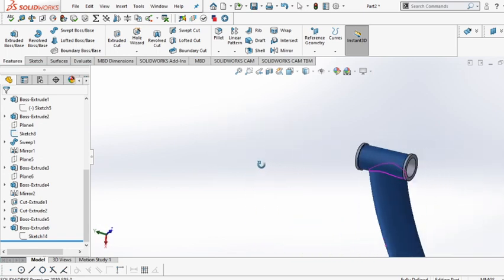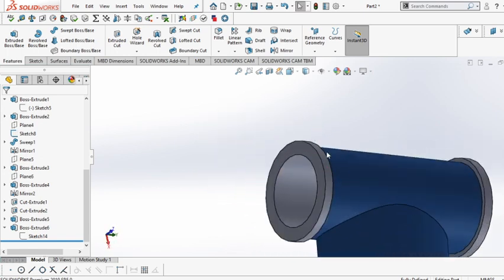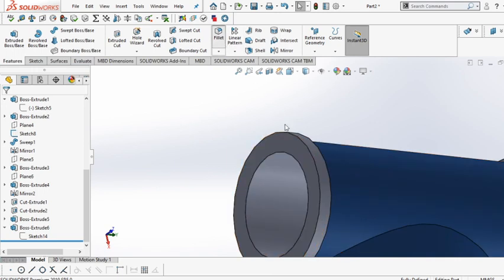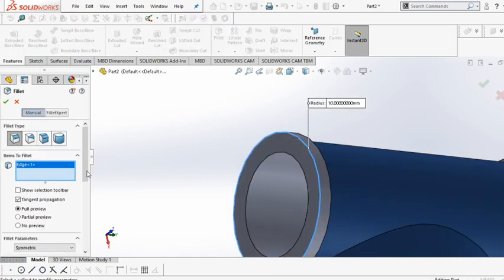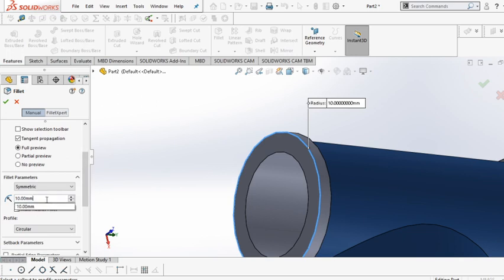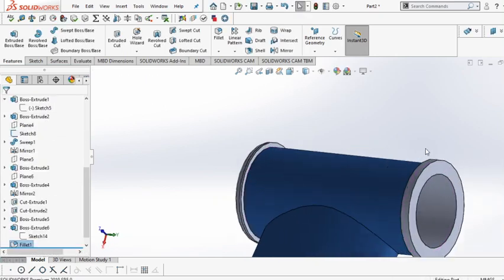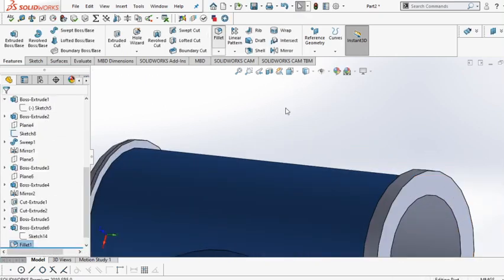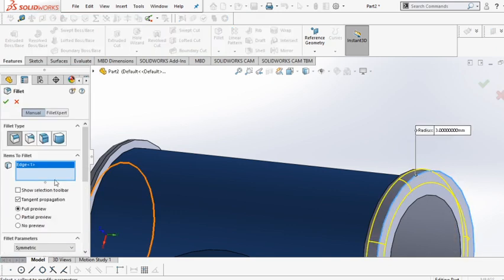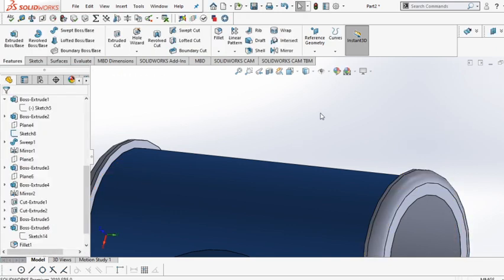And now you can pick, so fillet, add fillet for this face around, just say 2.0, or just say 3. Oh no, that's too much. 3 millimeters should be fine. And pick this fillet, take this face and give 3 millimeters. Just say okay.